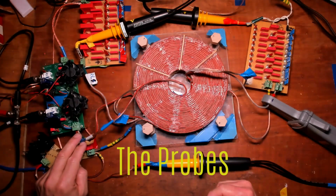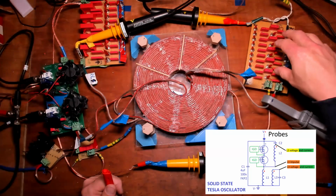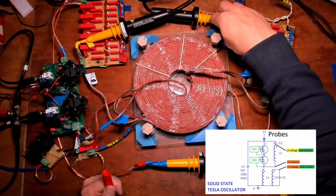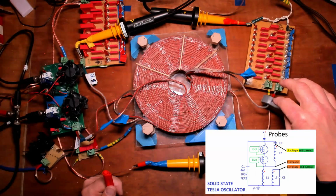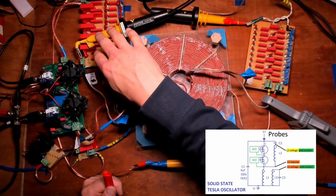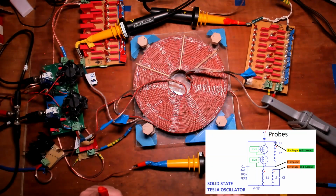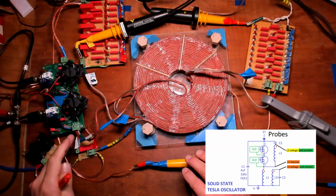Then the probes. I have got a current probe here. This is probing between the L3 coil and parallel tuning capacitor. So it's measuring the resonant current of the parallel resonance of L3. I've got another high voltage probe here measuring the voltage of L3. It's on the same point as the current probe. And here is a high voltage probe for the L2 series resonance. It is probing between the capacitor and the L2 coil, so we can see the voltage there. And I've got another high voltage probe here that is measuring the impulses created by L1 on the source.